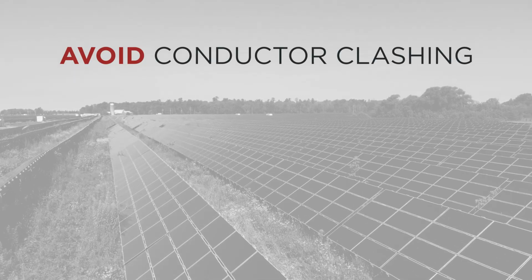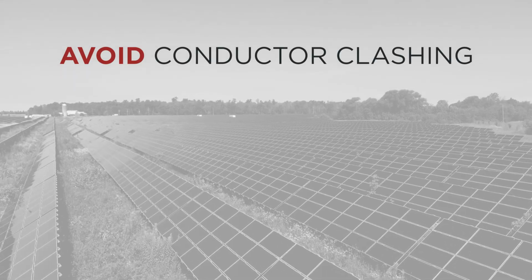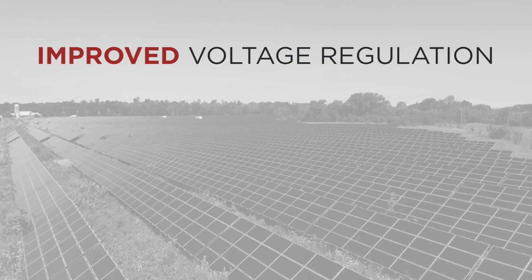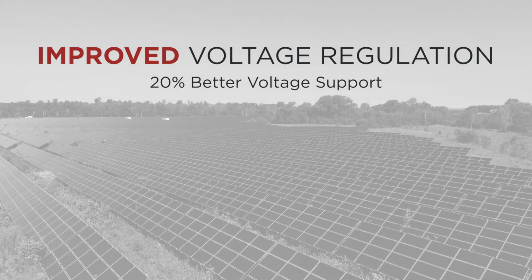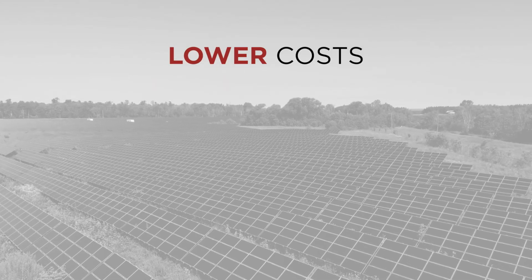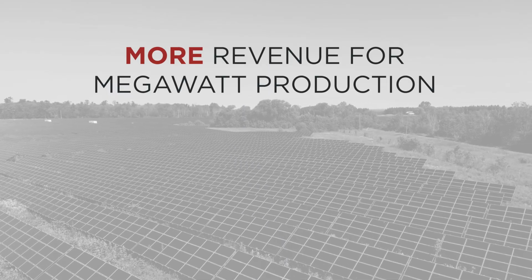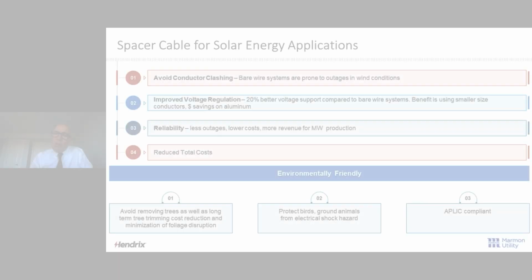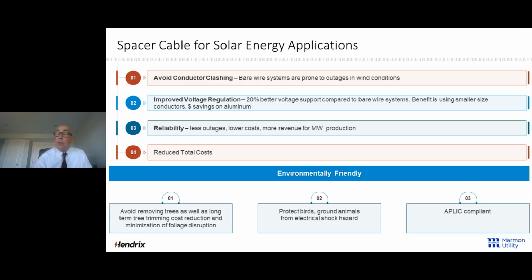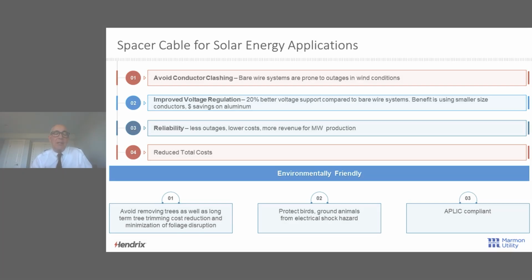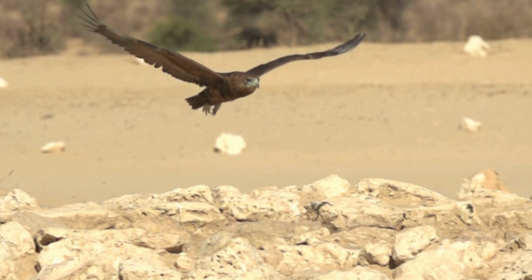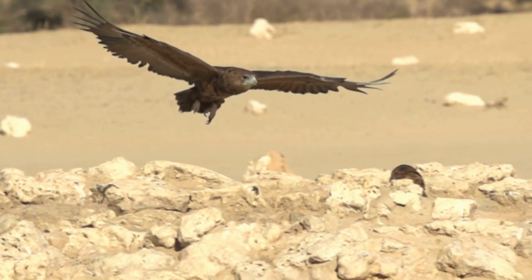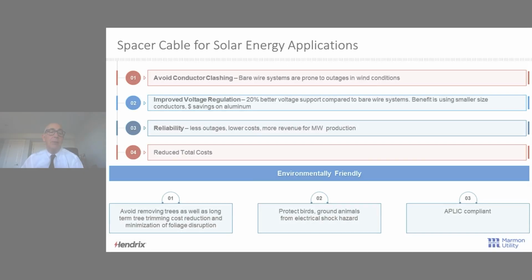At solar energy sites, we're going to avoid conductor clashing. We know bare wire systems are prone to outages in wind conditions. We don't have that improved voltage regulation, 20% better voltage support. We're going to have much better reliability, fewer outages, lower cost, more revenue per megawatt of production, and reduce the total cost. But really important in solar energy facilities is that they be environmentally friendly, that they be APLIC compliant. So, we're not sweating so much about removing trees out in the desert, but we are concerned to protect birds and ground animals from electrical shock hazard. That's a real benefit out west.